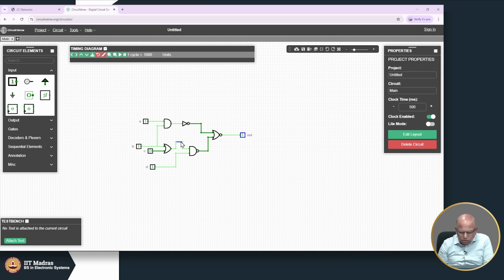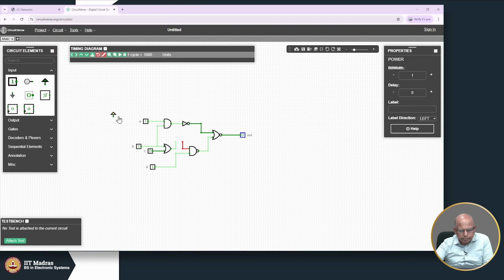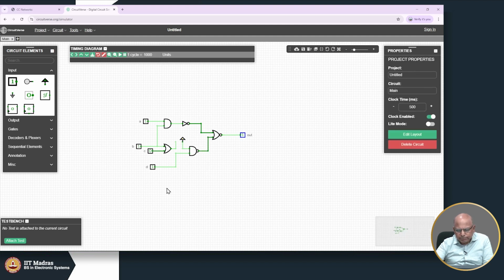Similarly, if you wanted to generate a test for a stuck at 1 fault, introduce a stuck at 1 fault like this by injecting a fault. Now, the faulty circuit also produces a 1. So, 1 1 0 1 is not a test vector for this particular fault. So, let us see, we are propagating the fault to this guy, and okay.